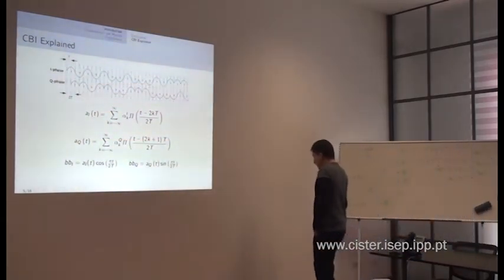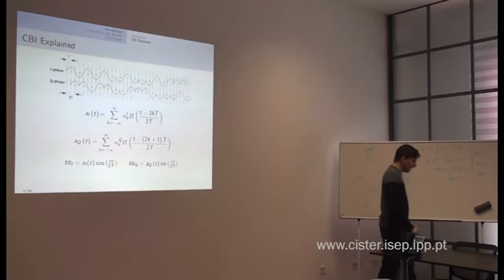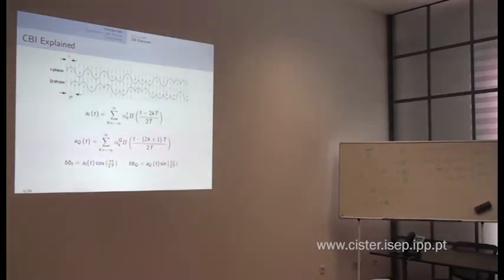If we look into low power wireless networks, what we typically have, at least in 15.4, which is the standard in which most wireless networks operate, is something called offset quadrature phase shift keying, which may be familiar to some of you. The signals are more or less like this. This is the information you want to transmit, and the bits are interleaved. So originally you have 1, 1, 0, 1, 1, 0, 0, 1.